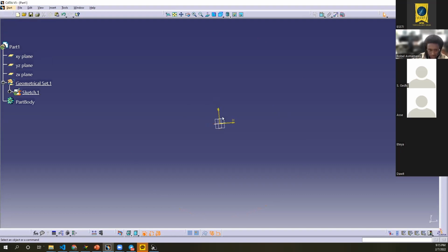Basically, you press both of them together, and you just do like this. This is how you move within the CATIA. If you want to know more about how to do that, you can always go on Google or YouTube and find out about it. If you want to go back to how it was before, you see this button right here, the I button. This is called the normal view. You press it and it will take you back to that normal view, meaning you will have a perpendicular view to the screen. That's basically what it means.